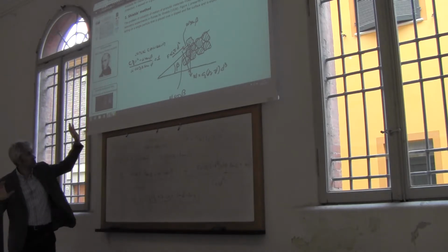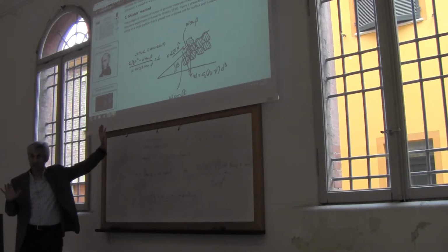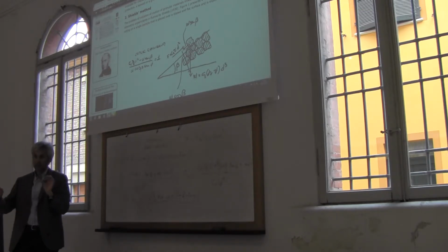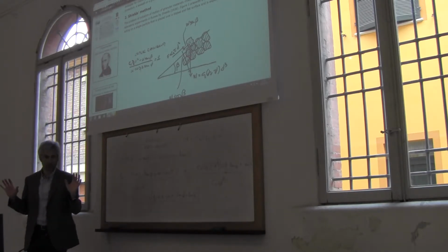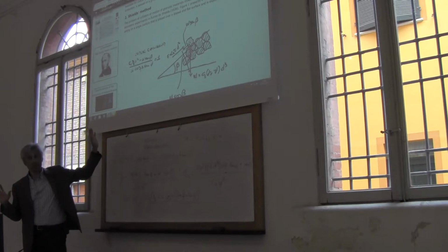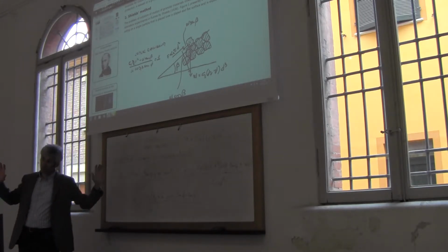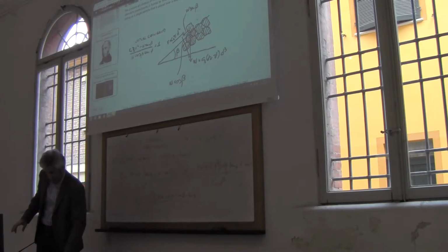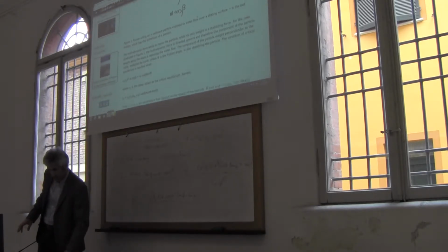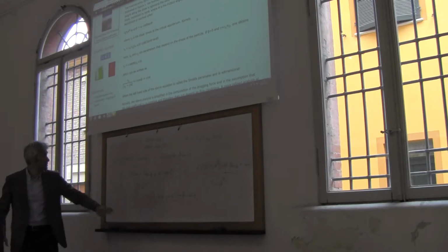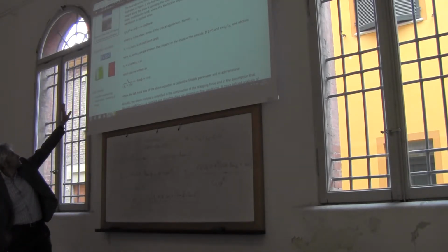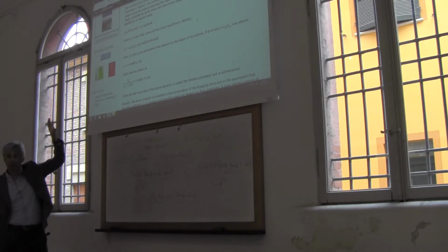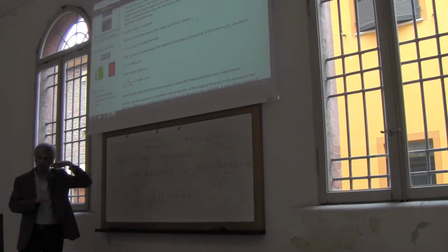So what we did is to study the equilibrium of these forces. Why did we study the equilibrium? Because we are interested in the situation in which the stability of the unit is critical. And therefore, for this reason, we equated stabilizing and destabilizing forces. So what we did is to write this equilibrium relationship, which is reported here, where basically we put on the left-hand side the difference between the hydrodynamic force and the component of the weight that is parallel to the side.